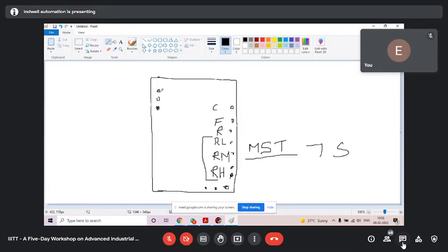On the AC drive, we have analog terminals. First, let me tell you about the analog input, AI, the analog input terminal. You can have current type and voltage type, both terminals will be available. So it is your analog input terminal. There you will get both options.